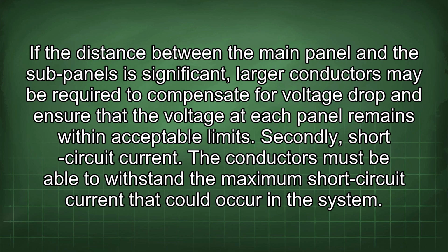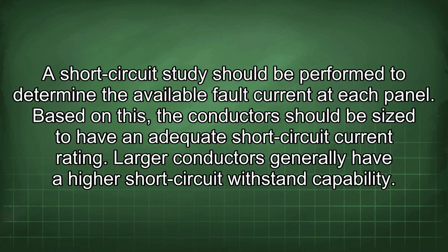Secondly, short-circuit current. The conductors must be able to withstand the maximum short-circuit current that could occur in the system. A short-circuit study should be performed to determine the available fault current at each panel. Based on this, the conductors should be sized to have an adequate short-circuit current rating. Larger conductors generally have a higher short-circuit withstand capability.